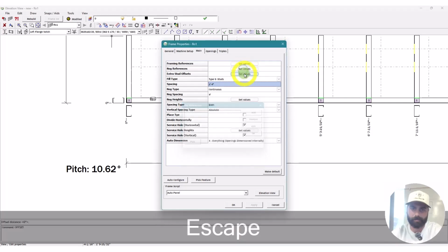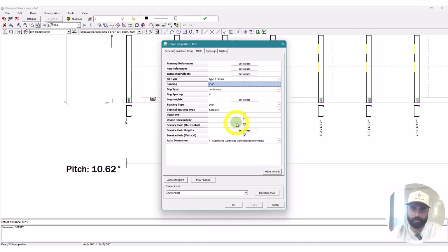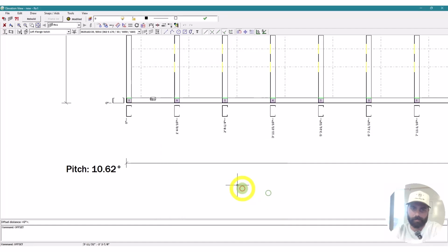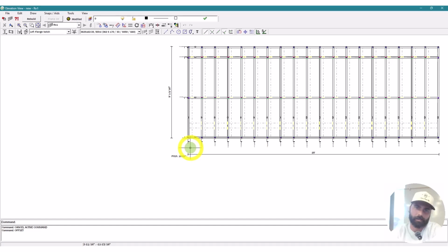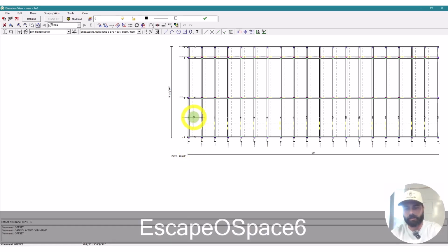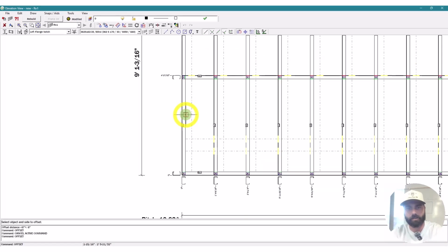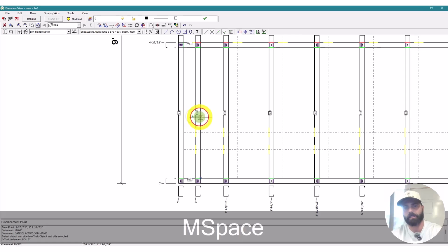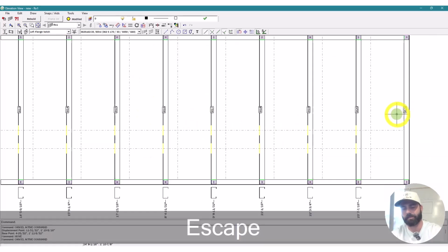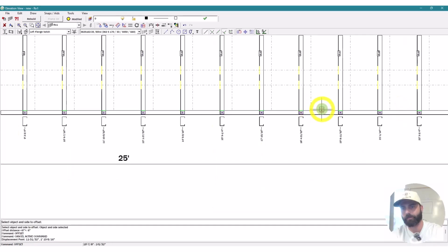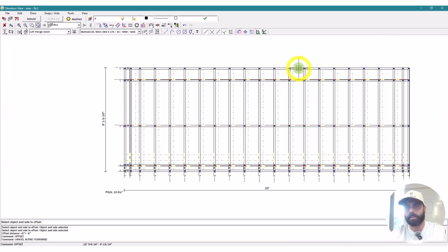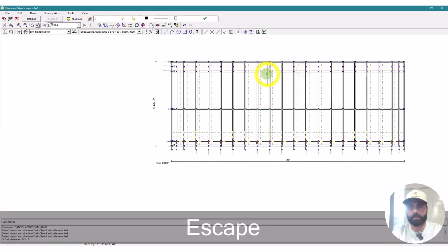So we can offset these 6 inches. So we'll typically create a stud that is aligned with the outside face. Offset. And this gives the guys something to do to align with their hands. So that way they're not trying to guess where 6 inches of overhang is throughout the entire project. They can just line it with their hands and make sure that it's in place.